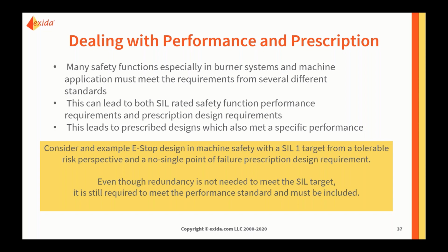However, there is almost always a separate requirement in addition to the performance requirement, which says that there can be no single point of failure in our e-stop design. So even though the redundancy is not needed to meet the SIL 1, the redundancy is needed in the e-stop design to meet the no single point of failure prescription requirement in all of these. So again, that is something that we need to keep our wits about us in making sure that we don't ignore a critical set of requirements in all of this.